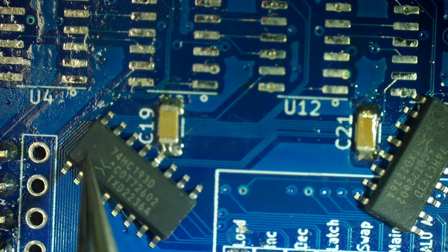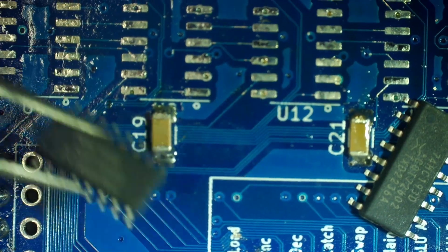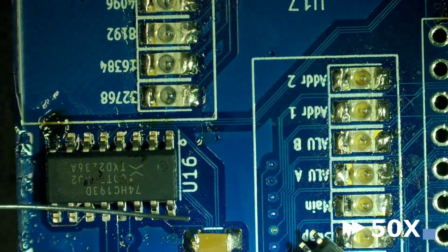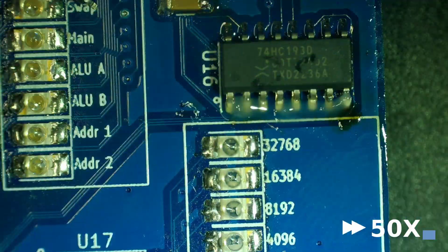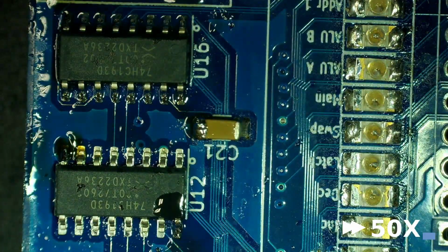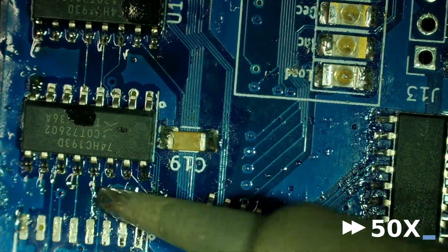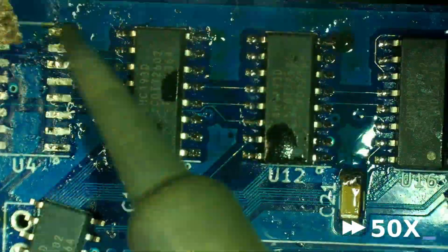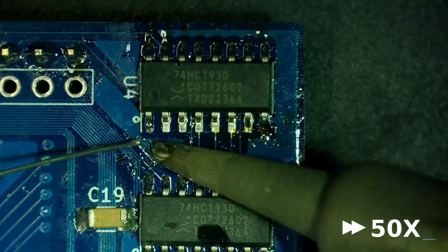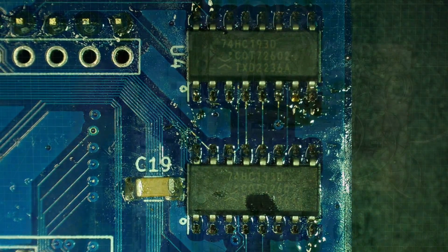Looks like I've got a marking here to indicate pin 1 that needs to go towards me. Okay, one thing I realized as I was performing the cleanup after completing the soldering is I had exposed a couple of copper traces. I'm not exactly sure if that's going to cause a problem or not, but it's certainly something I need to keep an eye out on as I'm going through and performing my testing. I may have accidentally bridged something without even knowing it. All right, now I need to clean it up and figure out how to test it.